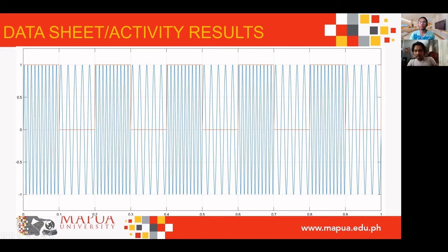So here the relationship of the pulse signal is that it acts as the digital input, where the carrier frequency is varied as mark and space symbols. For the mark, it has a high frequency at 1 or the on state of the pulse signal, and the frequency for the off state or the space symbol is low frequency and the amplitude is 0. Again, at the mark symbol or level 1, a higher frequency is observed. Then at the space symbol or level 0, a lower frequency is observed. Then the bit rate of the pulse signal is equal to the baud rate of the carrier signal.